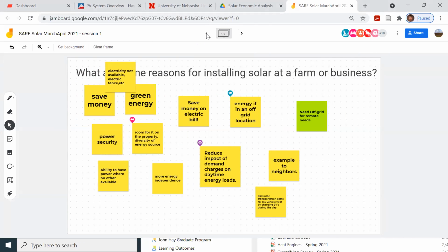So that's a good question for a developer or for an installer. If you have demand rates on your farm, has your modeling accurately compared your hourly weather data, so that we see hourly production, to the hourly load profile on our farm, so that we know what the impacts of demand rates are on this? Because I can say in most instances with confined animal housing, demand charges really make a tough economic case for installing solar.